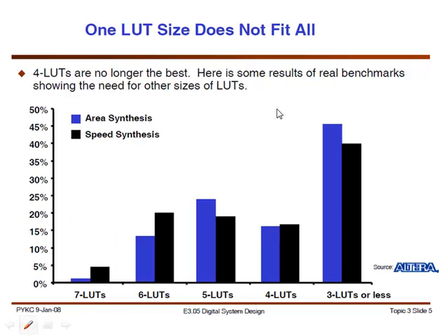If you think about gates, and we had our technology mapping slides as well, if I have a bunch of gates implementing something, and I want to cover this whole tree, then I need 6 inputs. So I can put the whole thing into one 6 LUT and hide all of these connections in between.